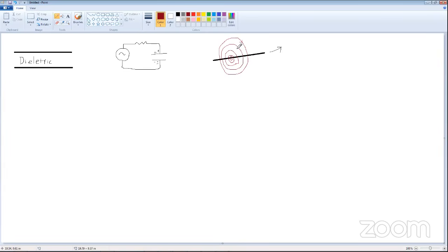Now, how they're rotating, you'll see in literature, there's something called the right-hand rule and the left-hand rule. Which one you use isn't important as long as you're consistent. So what you do is you align your thumb with the direction of current flow, which is this one over here. And then whatever direction your fingers curl in, that's the direction of rotation of the magnetic lines.